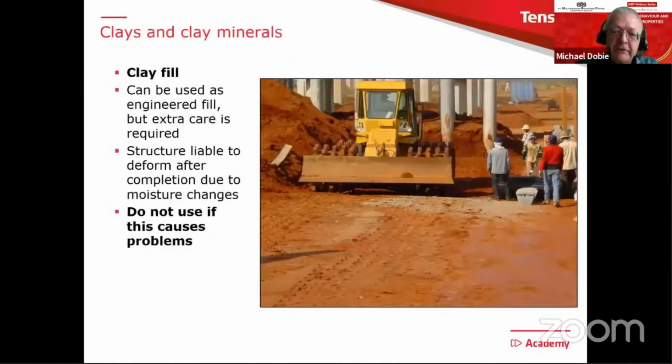Clay fills, yes, perfectly acceptable. In many situations, of course, we're going to use clay fills for highway embankments and so on, often for reinforced soil structures as well. We need to be aware that, in particular, some clays can suffer a lot of volume change, say from wet seasons to dry seasons. So they can change their volume, which means that they will deform. And if this is a problem, then maybe they're not such a good one to use in some situations. So you need to be aware of that when we look at clay fills.